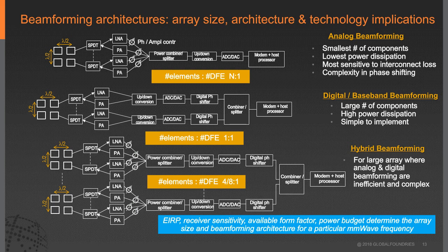Each of these phased array elements has the front end, and then it has the ADC stacks and the baseband. In the front end, you have the switch, the low noise amplifier, and phase and amplitude control. At the transmitter, you have the power amplifier, phase and amplitude controller, and the switch.